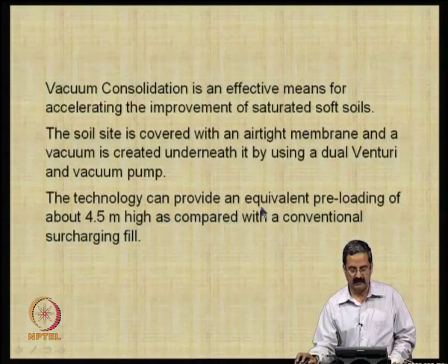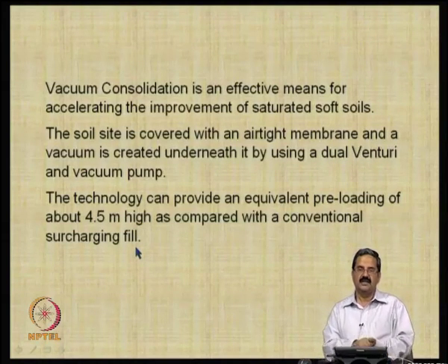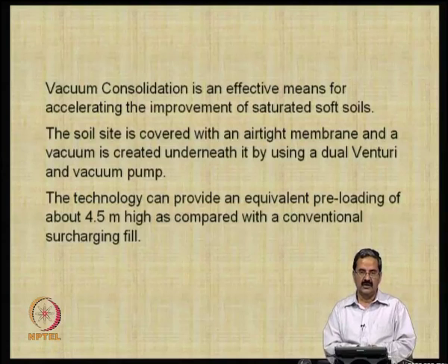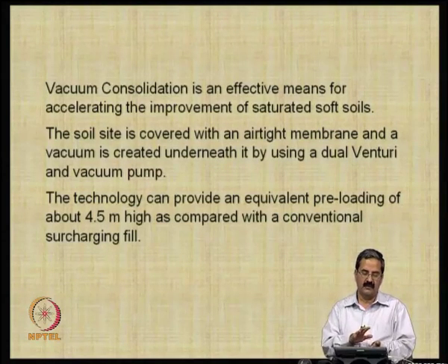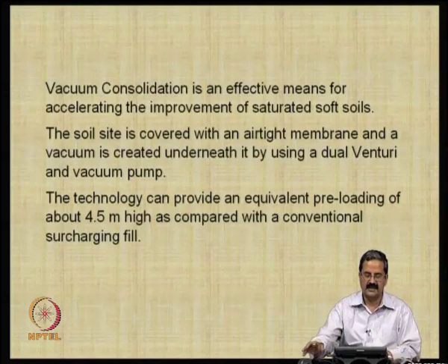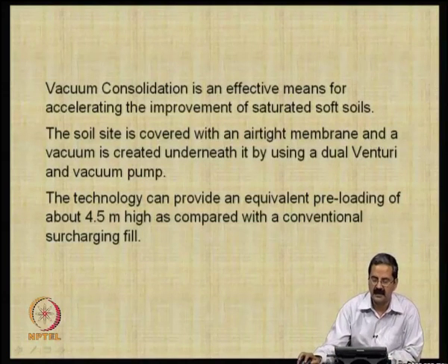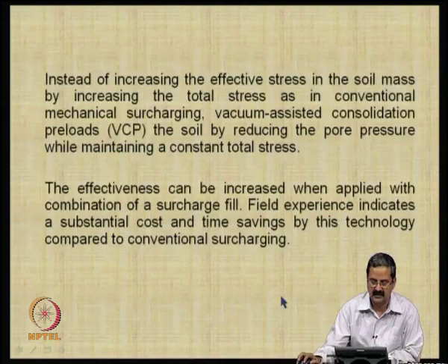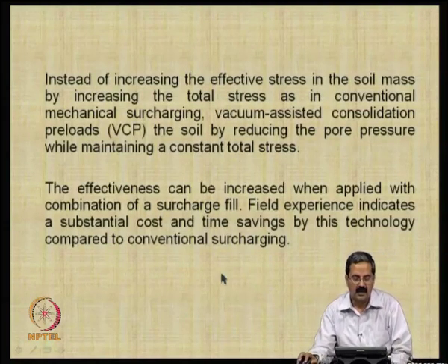The technology can provide an equivalent preloading of 4.5 meters high, compared to conventional surcharge fill. The advantage is clear: instead of going for 4.5 meters of sandbags or whatever surcharge, if you apply this vacuum properly, one can get a very good effect. Okay, so what happens here?